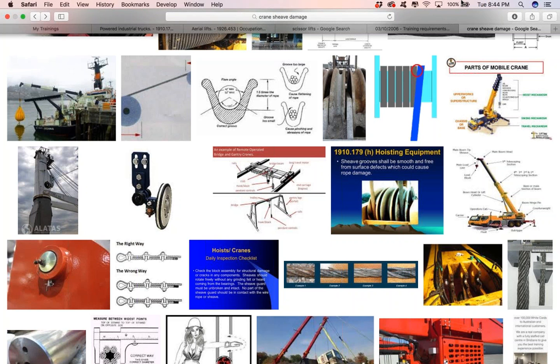One of the things I tell people is make sure you watch that swing radius, and also watch the height to make sure that we're not hitting any power lines or any other overhead obstructions, equipment, or fixtures. Also, be sure that everyone is in the clear while backing up, hooking up, or moving any attachments. We never move any buckets or shovels over the heads of other people. If you can't see the surrounding area clearly from the operator seat, we have to have a spotter, or you don't operate the equipment.